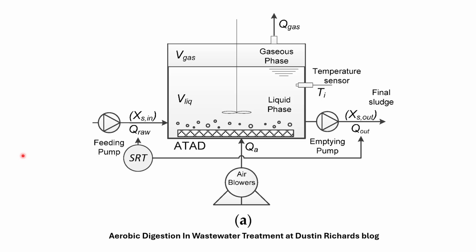Okay, and again, there's what we talked about, our inlet for our sludge. Here's the diffuser bubbling up air through here, and it's respiring, the microbes take in oxygen, munch away at the waste, and they respire CO2, that's the gas leaving.